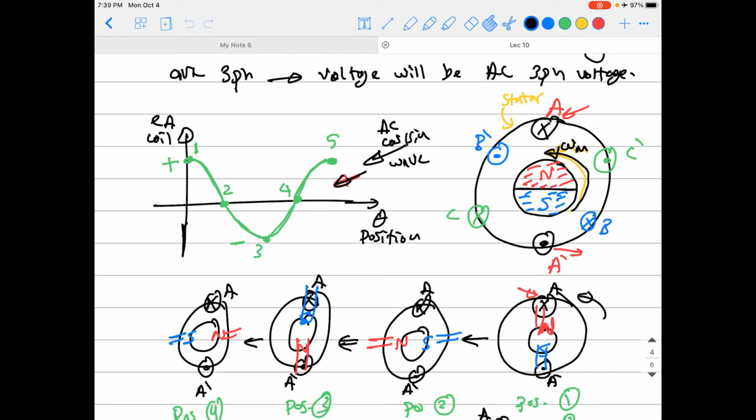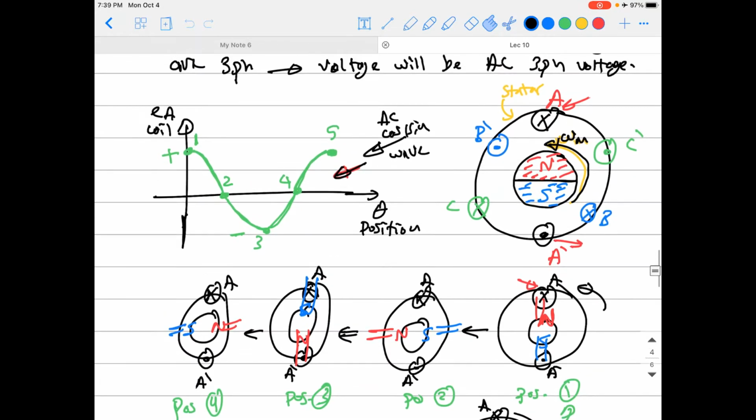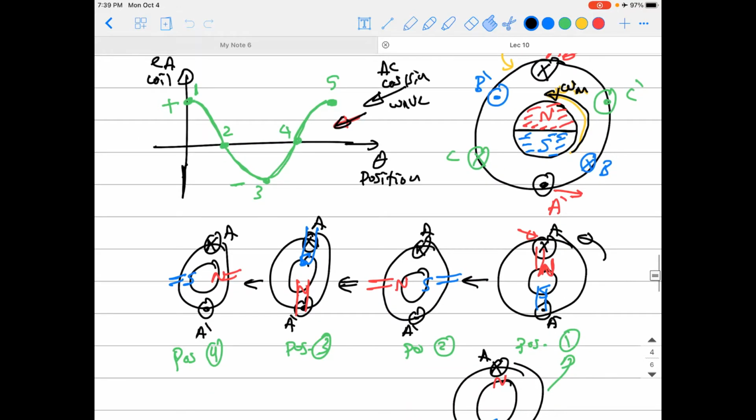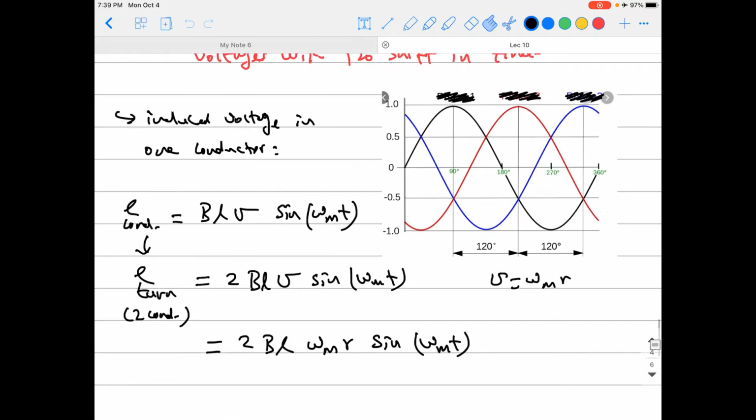Okay, and we derived that for each position of this rotor rotation inside the coils here, it will produce an AC voltage induced in each phase of them. And because these phases are spread around the circumference of the stator 120 degrees apart, the induced voltages will be typical sine waves. Each one of them will have a sine wave with the same magnitude, but they will all have 120 degrees phase shift between those induced voltages. Okay, so we will have a three-phase output like that, and that's what we need from this kind of generator, because it will be connected to the grid directly.